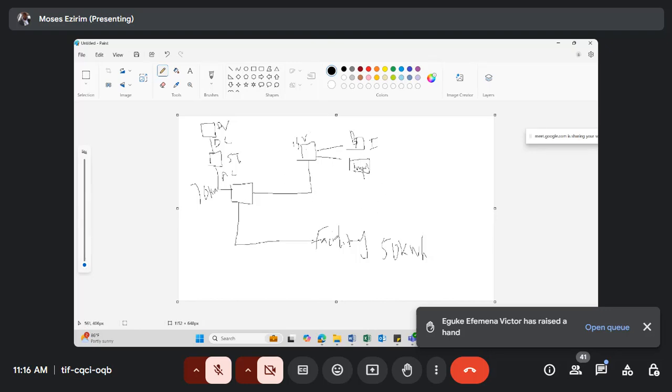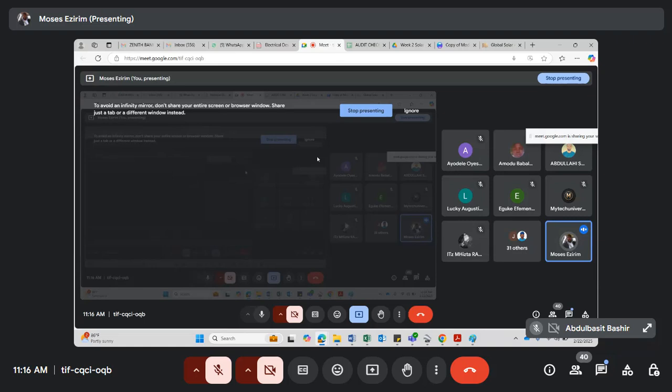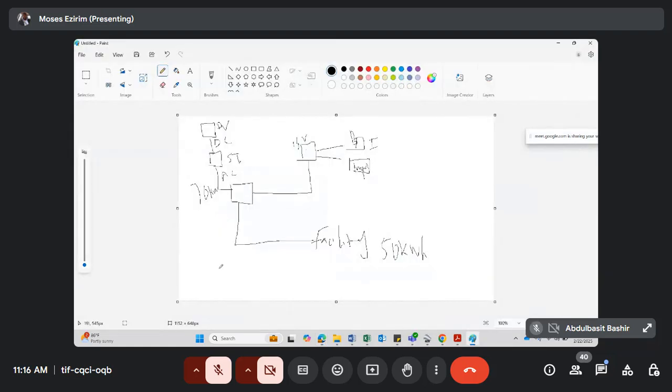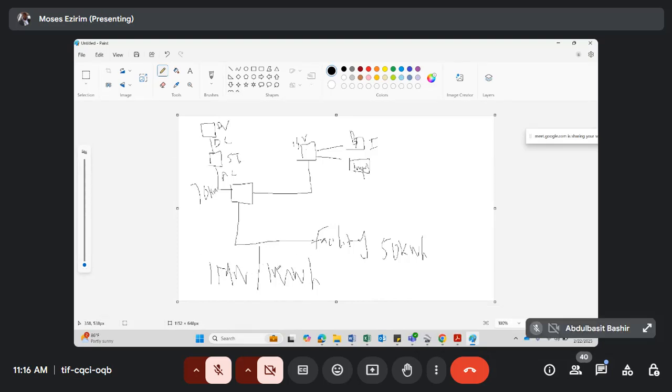Now, once you understand the flow, you can design any AC coupled system. And I'm sure you know that if you go to most facilities now, you will see where they put the capacity, like 1 megawatt, 1 megawatt hour. Have you been seeing something like this? Yes. This 1 megawatt is the battery inverter, which is otherwise called the PCS, the Power Conversion System. The megawatt hour is the storage.